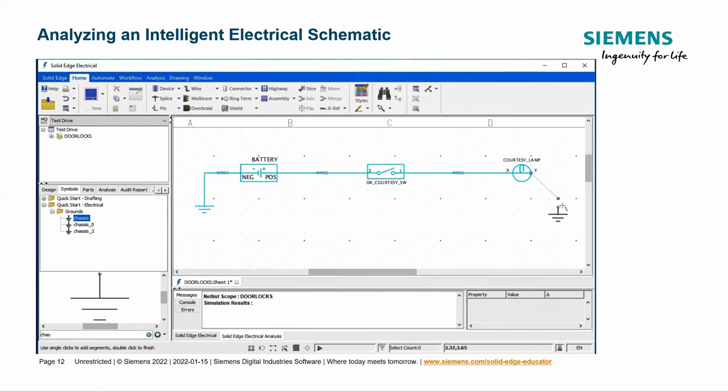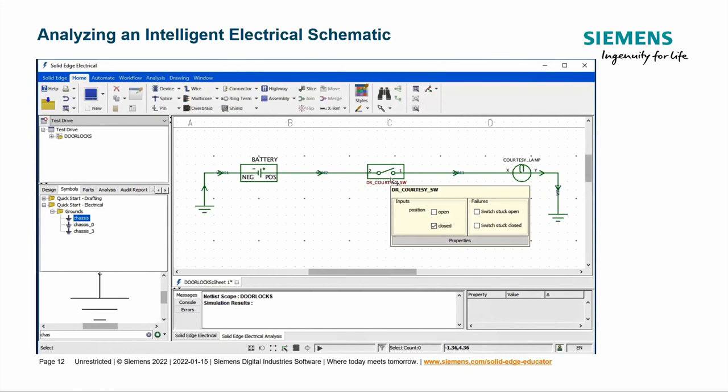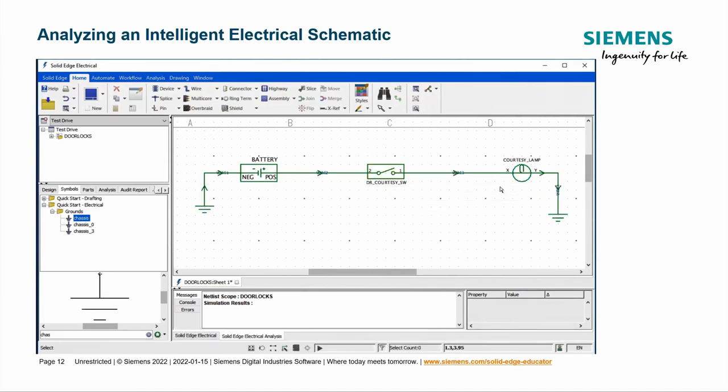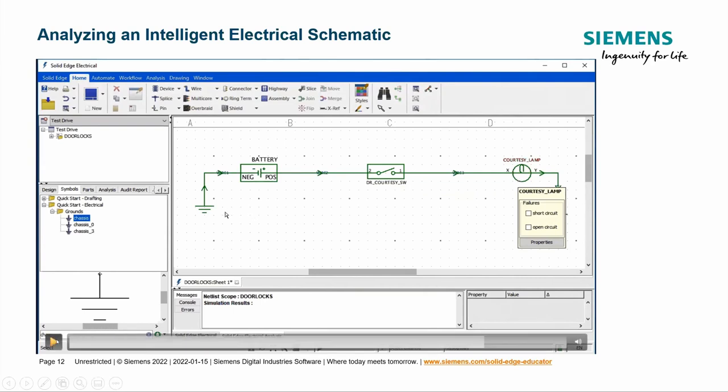See, this is an example of functional simulation. If we're designing, we want to make sure we don't skip a wire or miss something, because if we're building prototypes and we don't update our schematic, we're not going to find this out until way later when other people are looking at the prototype, and that could be costly to fix. So here they close the switch, and then we find that the lamp is actually working. So that's an example of simulation here.